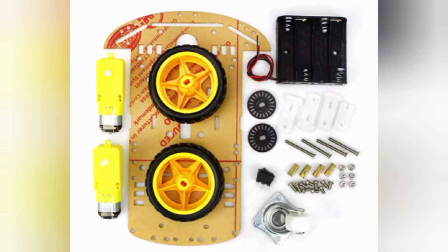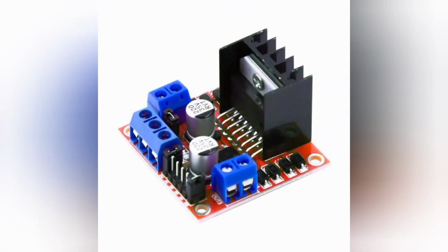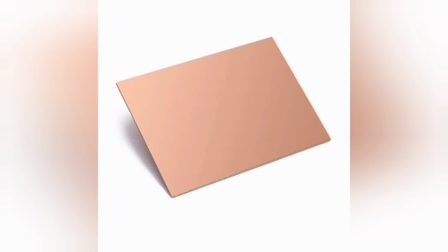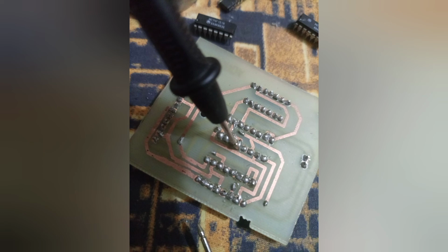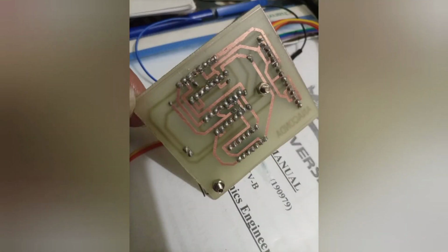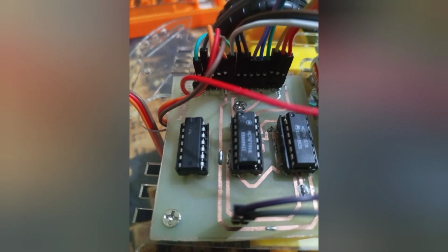For its entire construction you need the following: a rover set with the battery jacket included, jumping wires, L298N motor driver, battery cells of what you need, ferric chloride, and last but not least the double layered copper board. Here I will use printer jet ink as the maskant to apply all the pattern. I have used the ferric chloride to perform the etching operation, and after soldering I have created the PCB, and here you will see that I have made the connections as in the previous Proteus diagram.